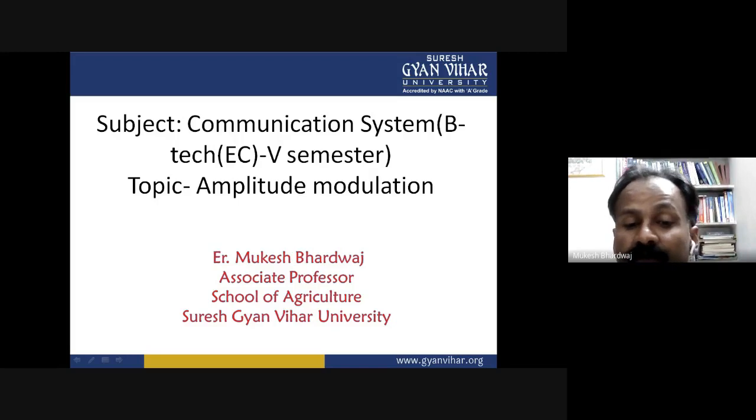Then according to amplitude modulation, the maximum amplitude A of the carrier will have to be made proportional to the instantaneous amplitude of the modulating signal x(t). So the standard equation for the amplitude modulation AM may be expressed as s(t) = [A + x(t)] cos(ωc t).